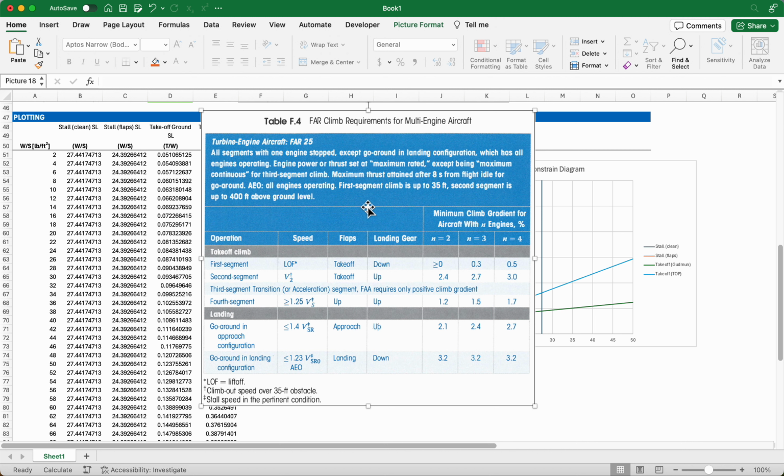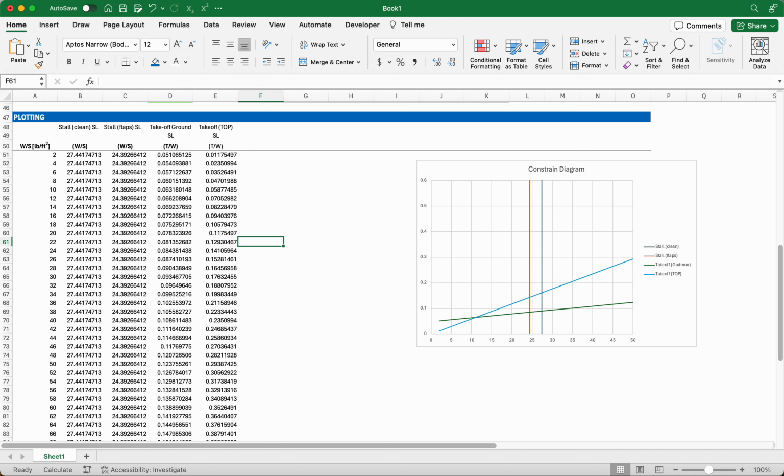You might also have just a general climb requirement based on a desired performance of your aircraft. So perhaps you want your aircraft to have a time to climb requirement, just like in our project where we're following the AIAA individual challenge. The aircraft has to climb to 65,000 feet, and it has to do this within 1 hour.